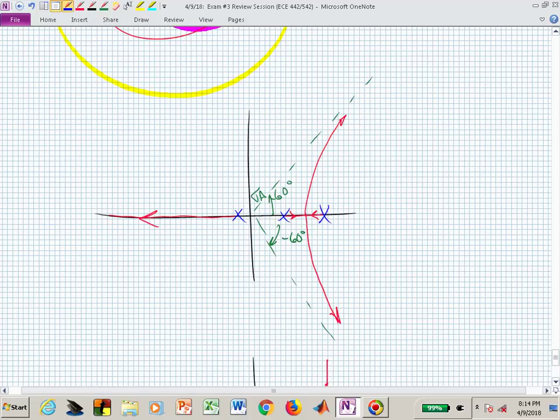And we also know that if we calculated the gain k between those 2 rightmost poles, where do they break away? At what condition? You can't tell me an absolute, but at the relative max between those two, and it may not be exactly halfway between because you've got a third pole that's influencing. So we would have to numerically or graphically determine the relative max between those two poles.